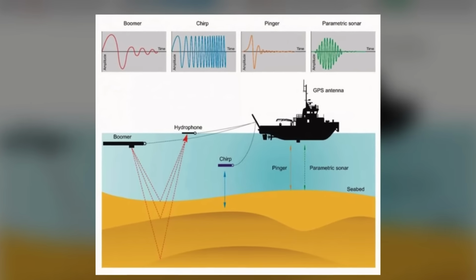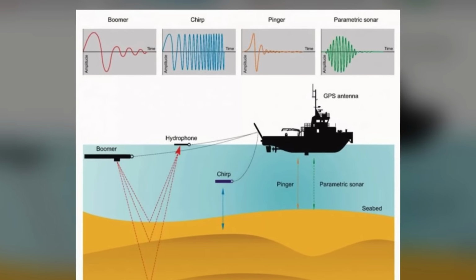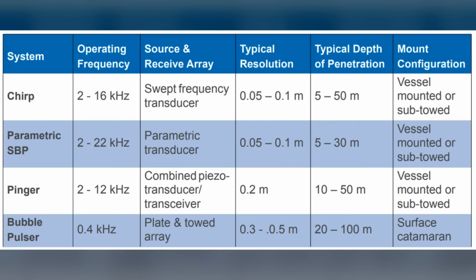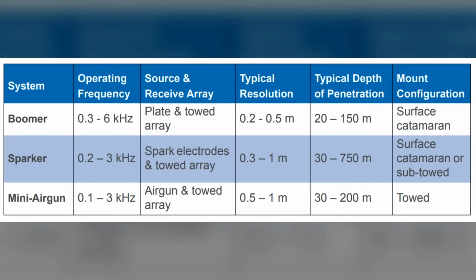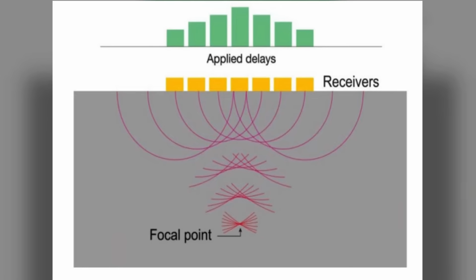In sub-bottom profiling, things are a little bit different. We have different frequency bands for different equipment. Some have a single frequency which you can select, and some operate on multiple frequency bands all at the same time. They all have different purposes and usage. These seismic waves propagate their energy in beams.